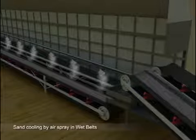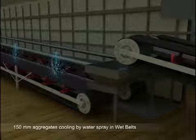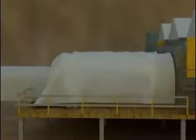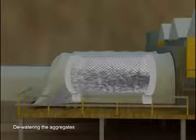The conveyors carrying aggregates of size 10 mm and sand pass through a chilled air blast, while larger aggregates pass through wet belts with chilled water spray with temperature of 2 degrees centigrade. To allow the extended time of travel for the aggregates in the wet belt, the conveyors move at a much lower speed. The temperature inside the wet belts is maintained at 4 degrees centigrade. Water from the cooled aggregates is removed by passing it through the dewatering rotating screen at the other end of the wet belt.